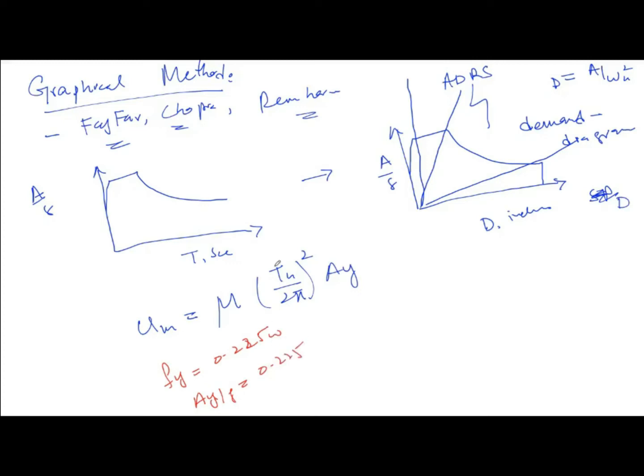So all the values on the y-axis of the capacity curve, for example, if we have a capacity curve like this, this is displacement, this is force. So it goes like this, let's say. So this force, which may be in newtons or kilonewtons, is divided by the weight in order to convert it into A_y by g. Then you can plot that curve.